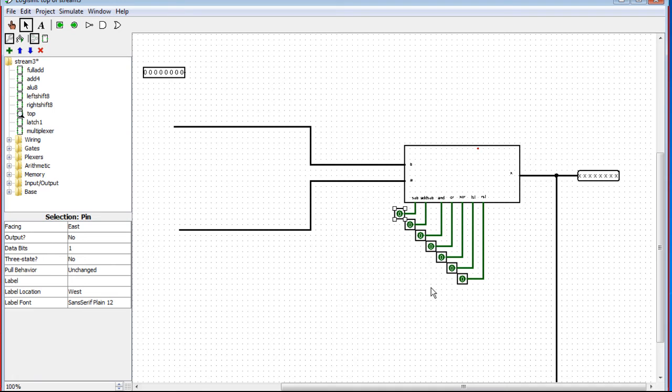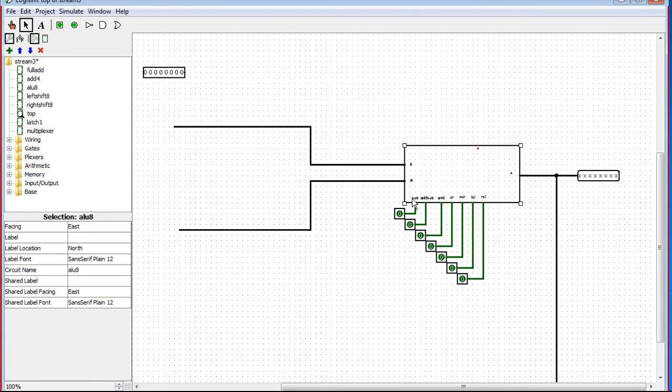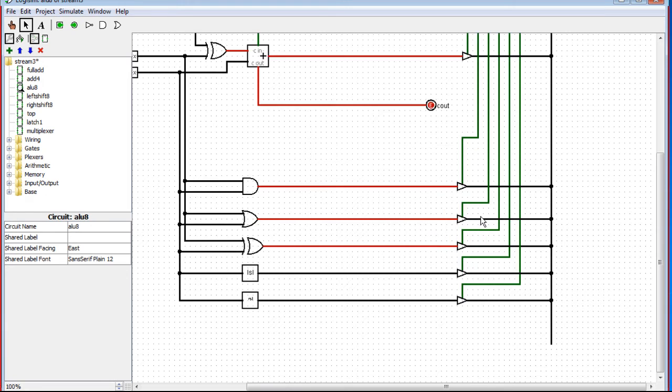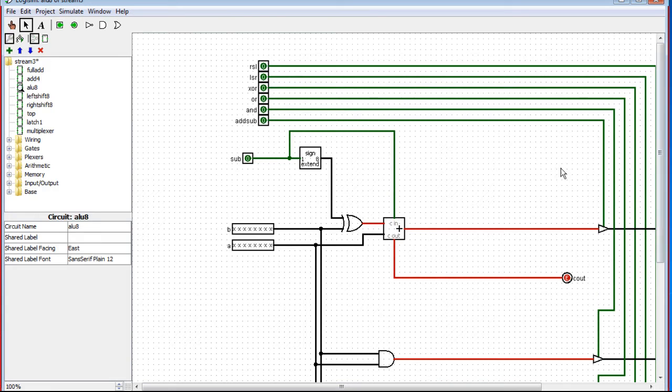All right. So what we're gonna do about these? Add, sub. All right. So first off, I don't like the situation where this line here selects add or subtraction, and this one determines whether it is subtraction or adding. So these two in conjunction select add, subtraction. I don't like that. I want every single individual line to select a different operation. So make a one-hot encoding here. So what we're going to do here is we'll just insert a little bit of logic.